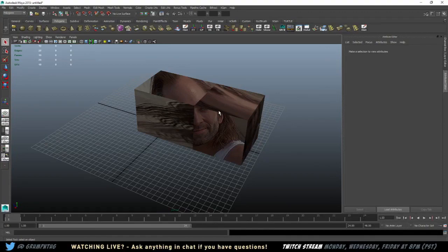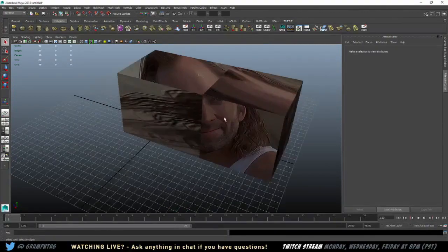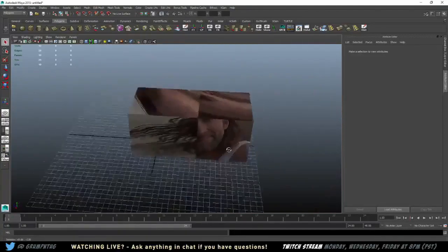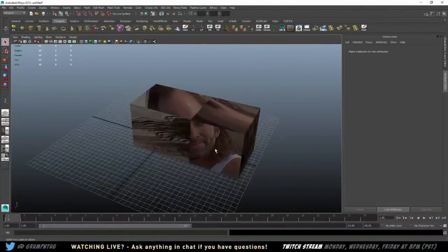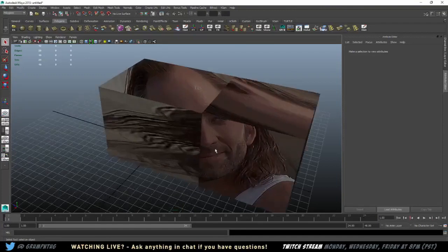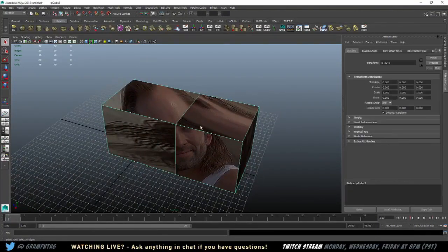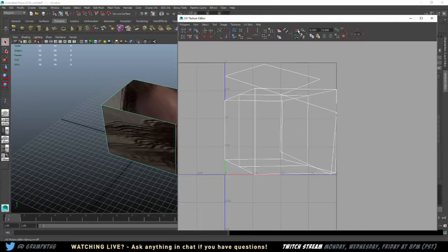So that's an important tool. I use that a lot when I'm making some kind of rubble or something. If I break some rock and I just have a broken edge of concrete that I need to map, I'll select the whole thing, rotate my camera right on it, and then create based on camera, and that does the entire thing. I don't have to do any weird plane stuff or weird things to try and make it work.